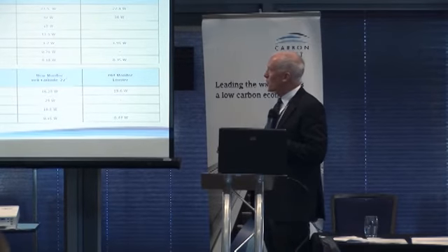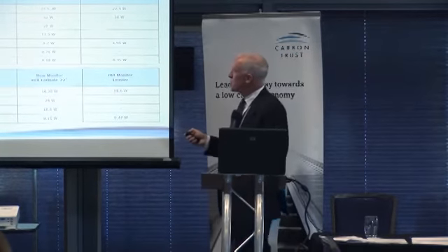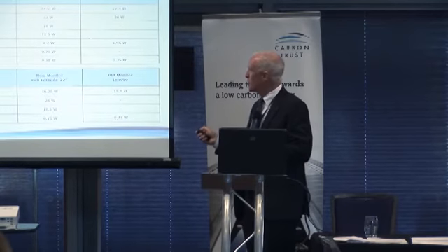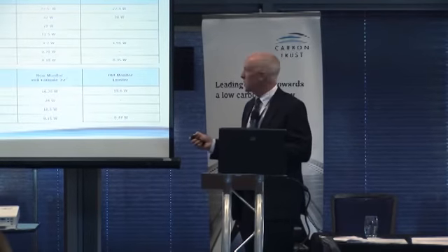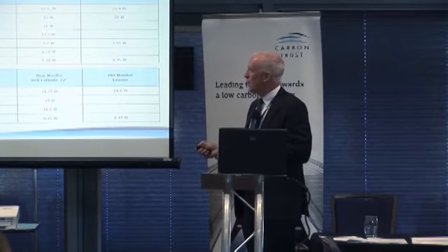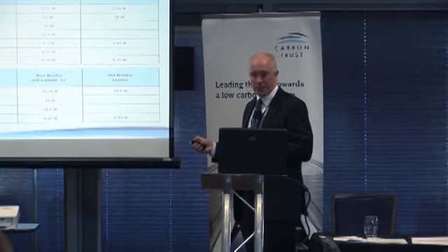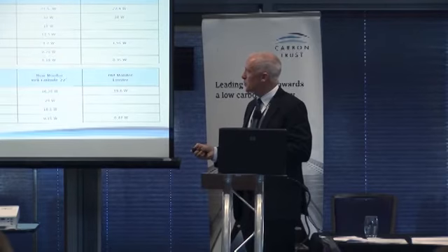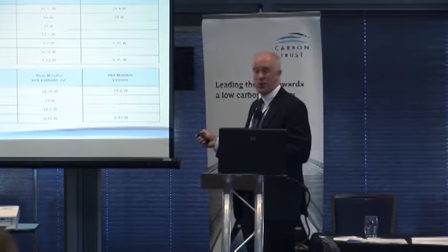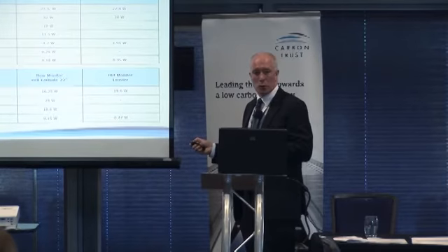On switch off of the laptop monitor, these are for two laptops actually, when you switch the laptop monitor off, it goes from 19 watts to 12.5 watts, so it shows you the laptop monitor taking about 6 or 7 watts there. In sleep mode, the laptop used to go to about 2 watts, the new laptop goes down to 1.2 watts in sleep mode. The docking station power, that's the transformer within the docking station, 0.75 watts, that's above the government standard of 0.5 watt. The laptop transformer itself used to be 0.35 watts, and the new one is 0.18 watts, so I think halving that.